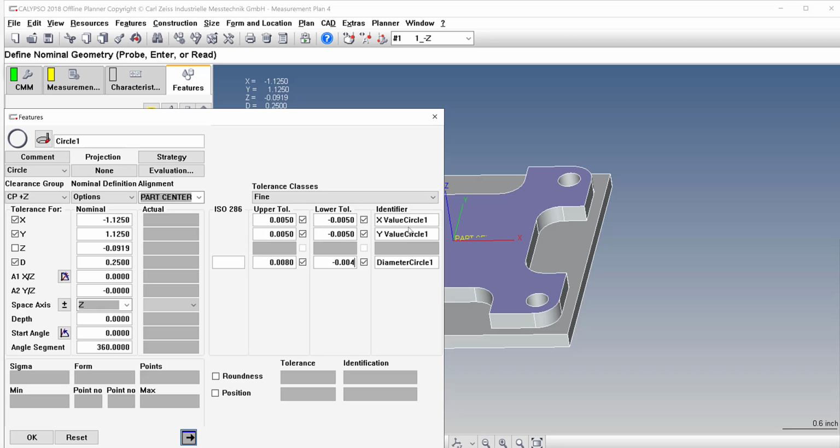And the X value of circle 1, all that stuff is great. The key thing here is that circle 1 needs to be documented on the drawing as the upper left circle. We could call it upper left in features, but I think that's a little bit cumbersome because this part is symmetrical, so we don't have an orientation for it. So we need to keep that in mind. So we could label these in the future, as long as circle 1 is noted.